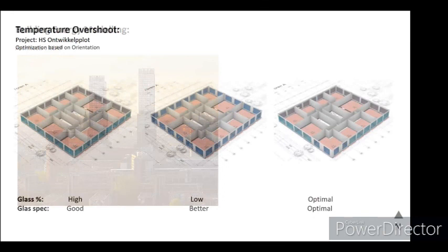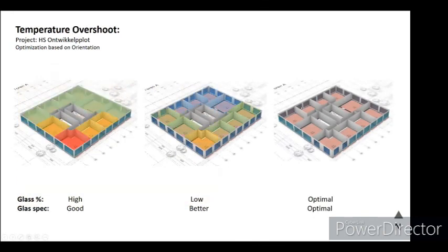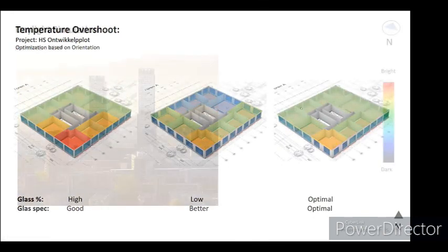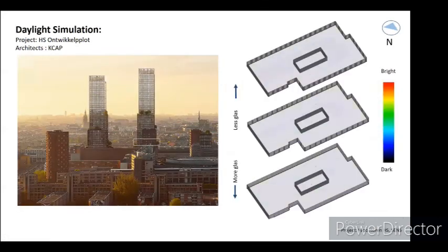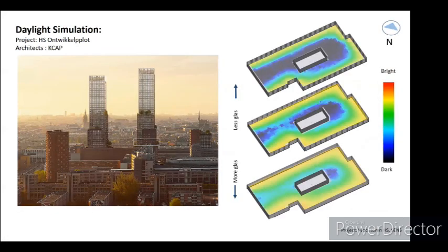And of course, once you understand what kind of glass percentage you are going to put based on the thermal comfort, then you work on the daylight simulation and see what kind of glass percentage is better or more suitable. So putting more glass or less glass and understanding the light transmission is very important over here.